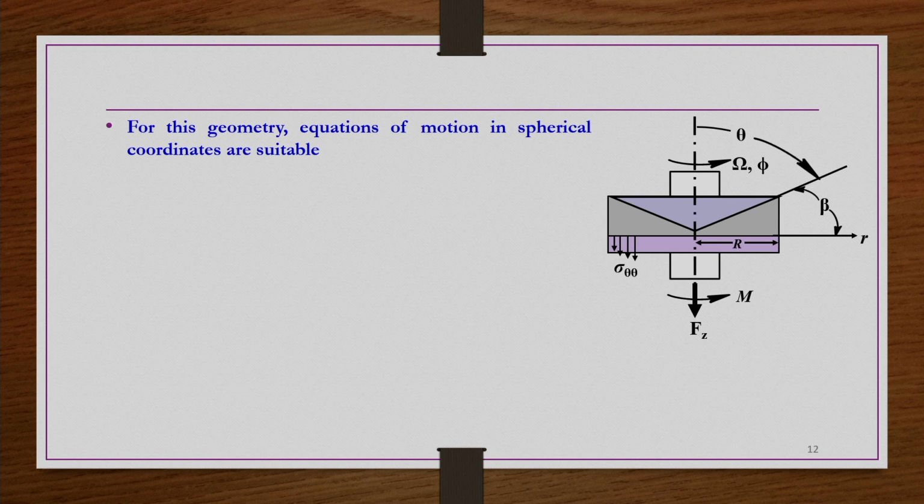Okay. So now here the cone angle is taken very small in general for most cone and plate geometry, because when the cone angle beta is very small, one thing is that you can avoid the curvature effect, and another thing is that the shear rate can be maintained constant. Okay. So the gap is narrow, so then we can say that shear rate almost remains constant. So that is the advantage.